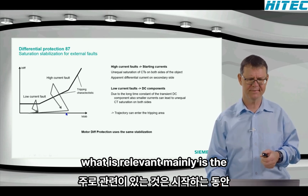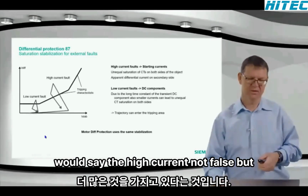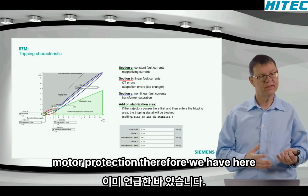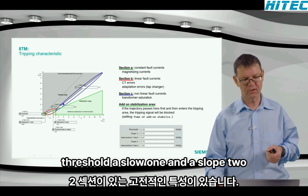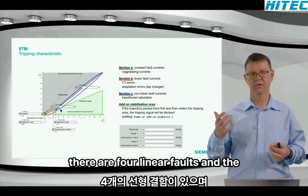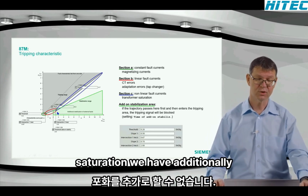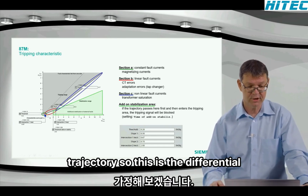What is relevant mainly is that during the startup, I have the high currents, not faults, but startup currents. I mentioned already we use the same principle because it works fine for the motor protection. Therefore, we have here our classical characteristic with a threshold, a slope 1 and a slope 2 section. The slope 1 is to compensate for linear faults, and the slope 2 is to compensate additionally for current transformer saturation. For the current transformer saturation, we additionally look at the trace of the trajectory.